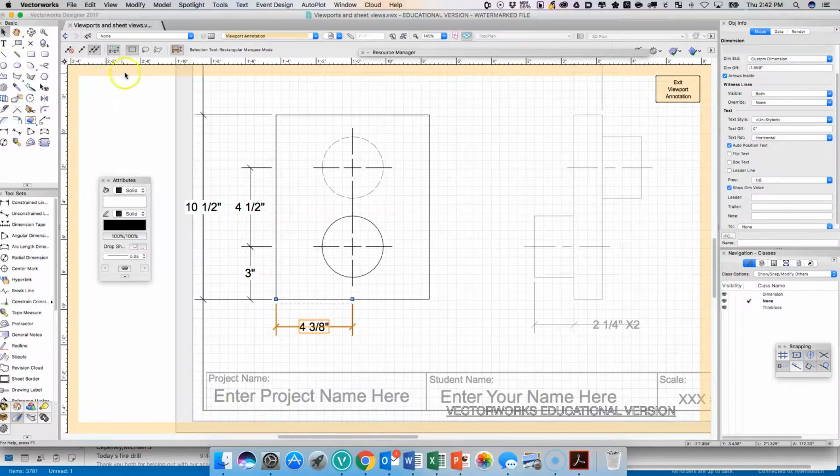So I'm going to select the dimensioning tool, the radial dimensioning tool. And if you remember, our modes up here are internal diametrical, external diametrical, internal radial, external radial. And if you're looking at this example with me, you'll see that it is an internal radial. So I'm going to select internal radial. I'm going to click, and it's finding that phantom circle. And here it has internal radial.